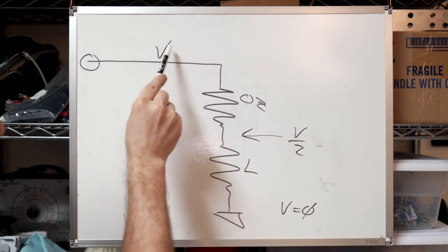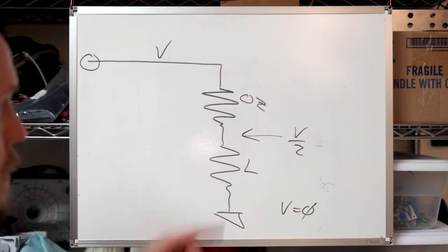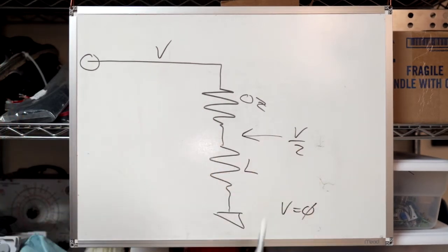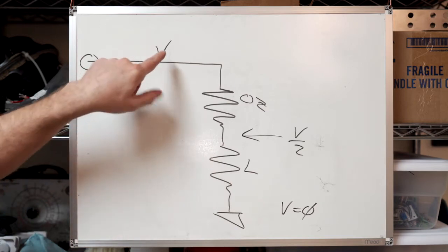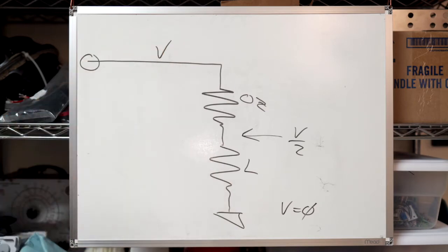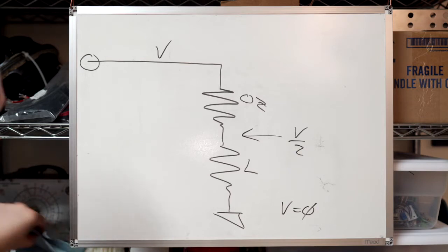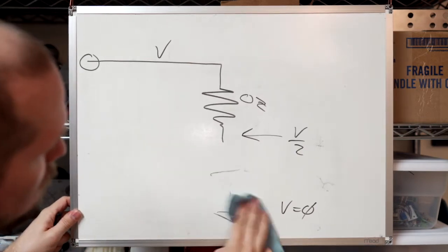you would measure here, and you would see that you've halved your voltage, right? We don't actually have access to this voltage directly, but we can find out what that voltage would be, because all we have to do is unload the output, right?